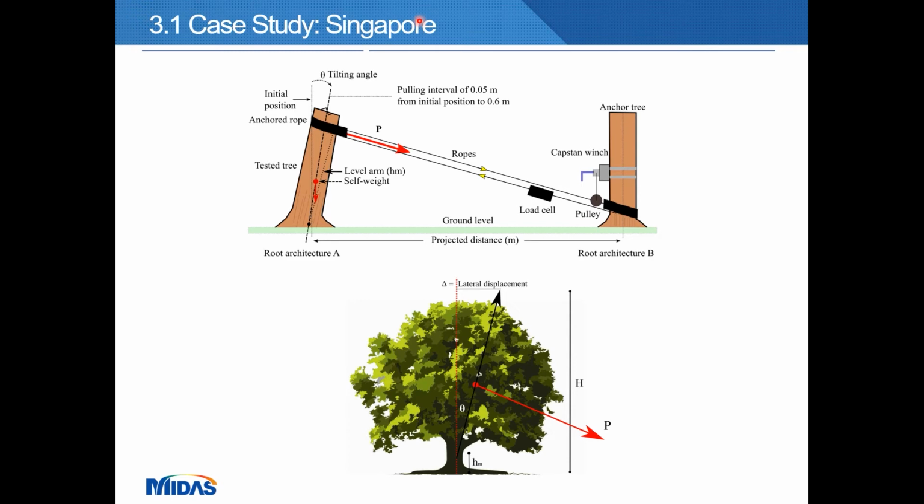And the soil foundation was composed of medium sand with a medium particle size, D50 around 0.4 mm, and a coefficient of uniformity around 3. The grain shape was characterized as rounded particles with medium sphericity, and the fines content was less than 10%.